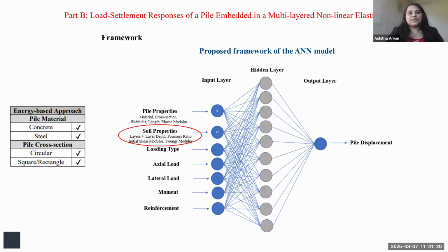So similarly, for part B, I gathered all the information for load settlement responses of a pile embedded in multi-layered nonlinear elastic soil strata. As you see here, the energy-based mode method was conducted for two pile materials, concrete and steel, and for circular and square piles.